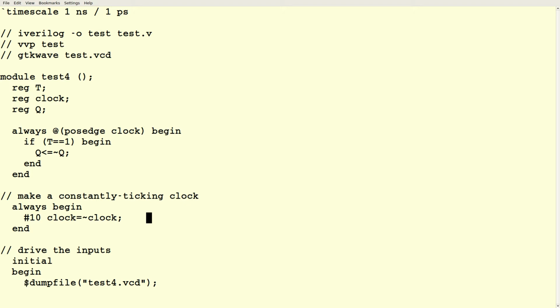But if we say, when the owl hoots 3 times, I want to take the output of the circuit and store that in this variable x, that's going to happen at one moment in time. And so that's got to be able to remember the value that you set it to. That's going to have to be a reg. So usually a reg is going to be a flip-flop, and a wire is just going to be something like a wire.